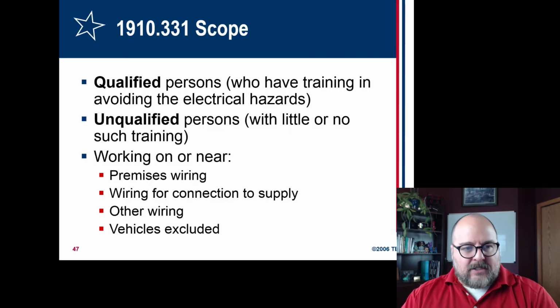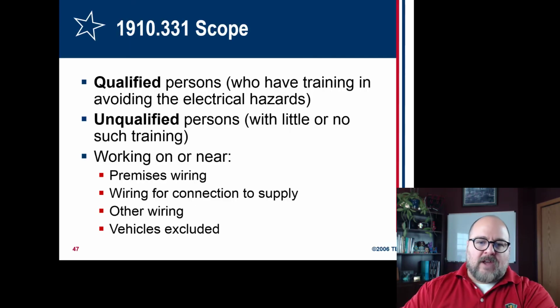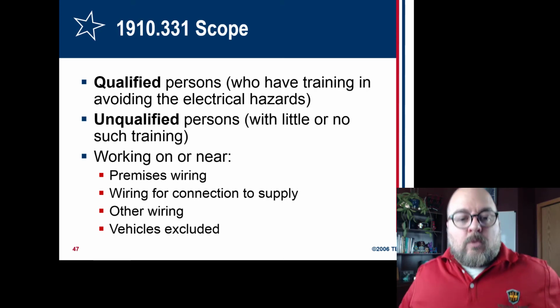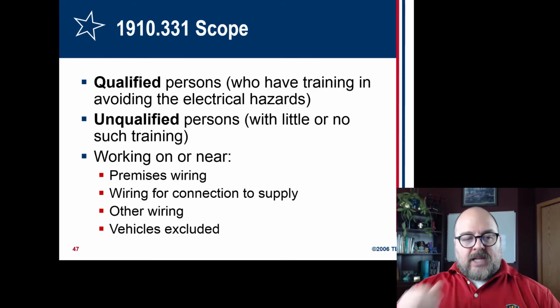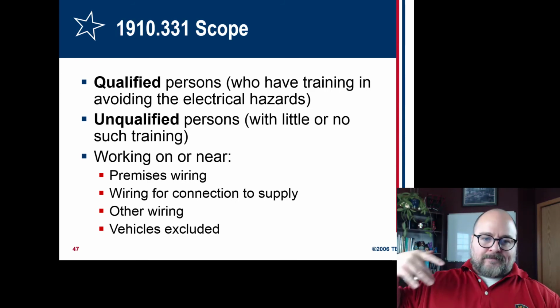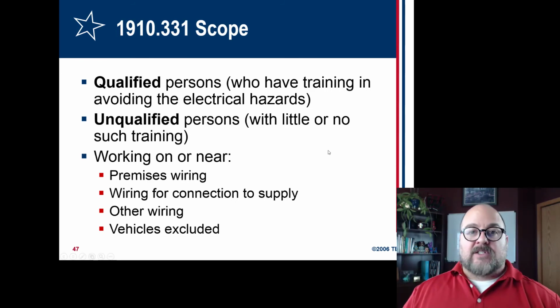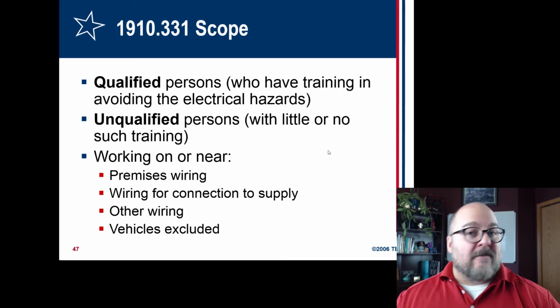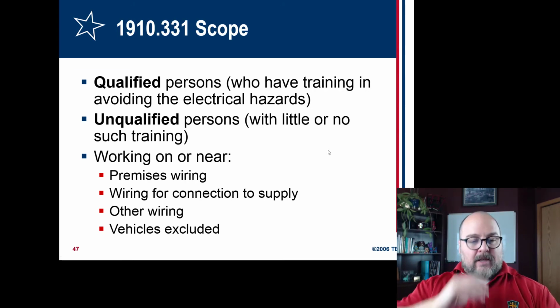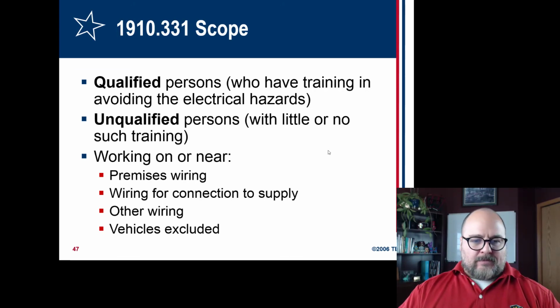Safety-related work practices. There are qualified people and unqualified people. Qualified are the ones who are trained to be around electrical hazards. Even though you do want to de-energize, unqualified persons should not have access to it. And that's everything above 50 volts. They can't go near it. Although I think there was a ruling, 50-60. So I think 50 is what OSHA goes by now.